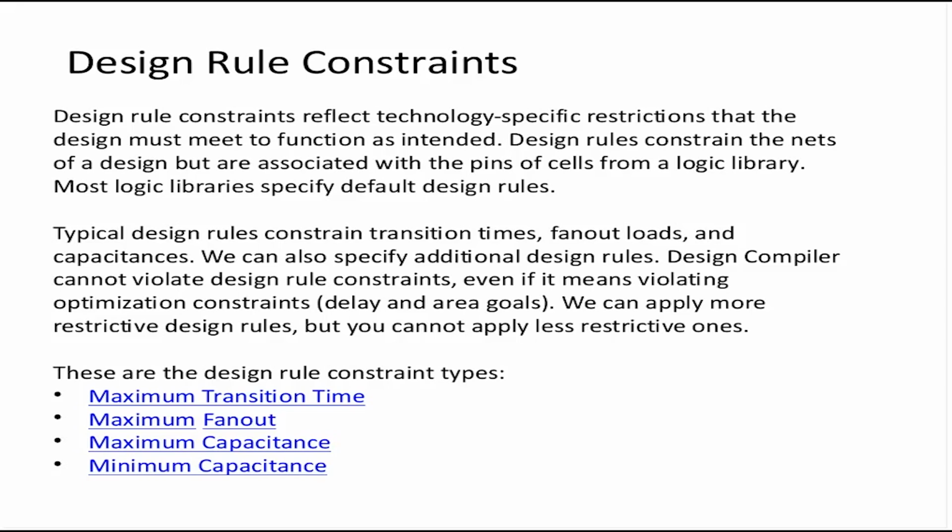The lookup table will have two indexes, the input transition and the output load. Each of these indexes will have a maximum value associated with it. That means the designer has put a maximum limit for the input transition and the output capacitance, and has run SPICE up to that maximum point. If the capacitance and transition go beyond those points, then the delay calculation is not deemed accurate, because extrapolation is happening.